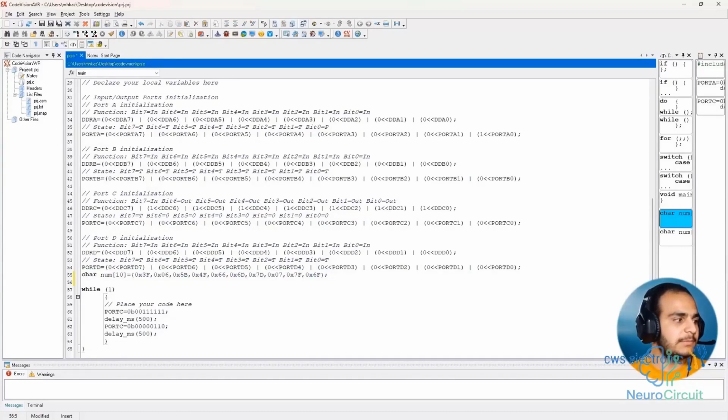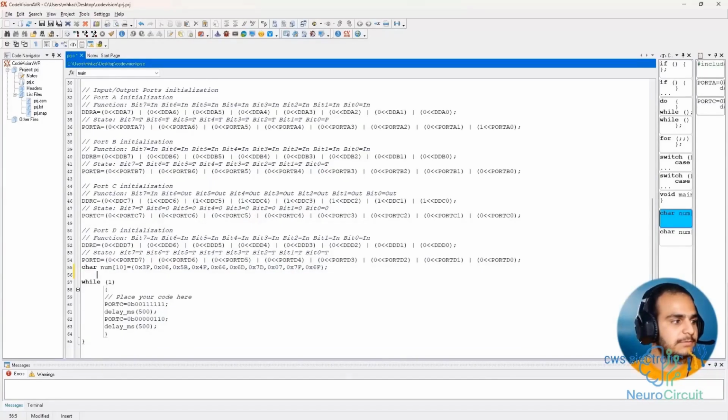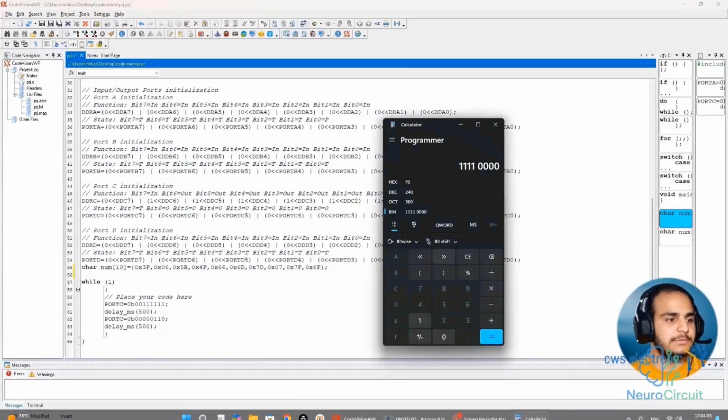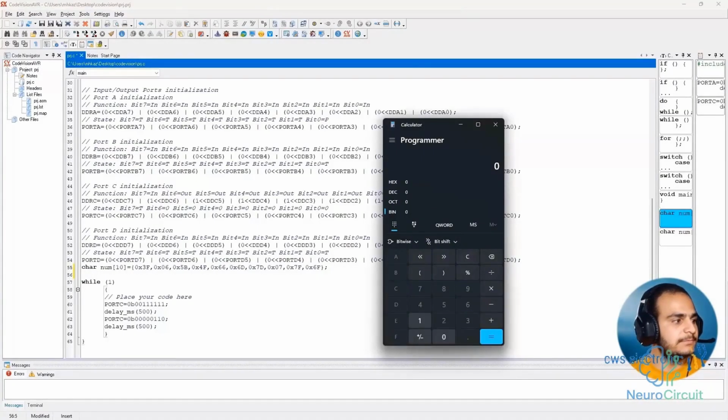But so that we don't get involved with arrays in the C language, I just want to put these numbers directly on the port. The point here is that, just to have a shorter code, the numbers are in hexadecimal, but like the previous project, it's enough for you to do the conversion yourself. For example, right now for the number 1, we have hex 0x06.